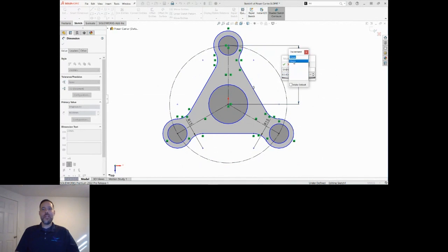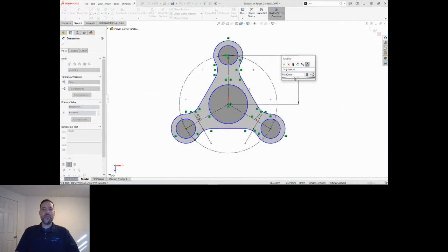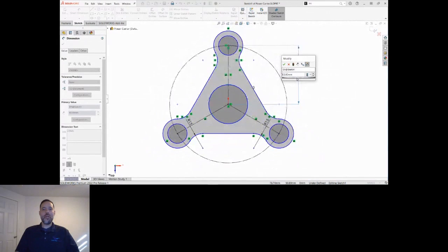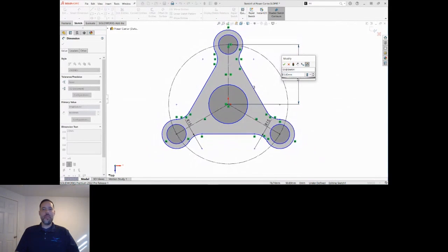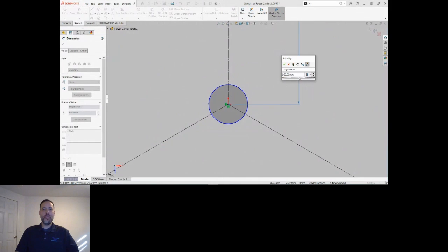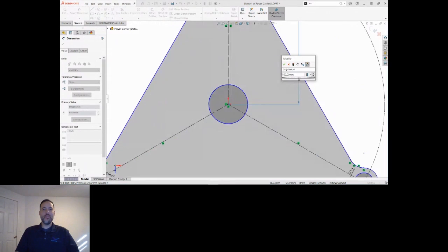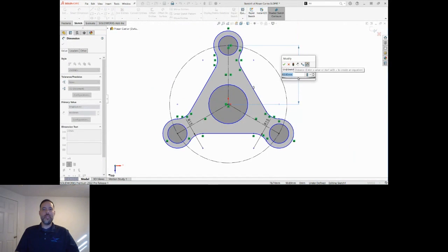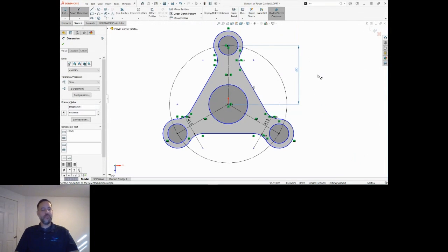So if you click on that, right now it's 10. If I click and drag this box, the spin box, there we go. It'll go up and down by 10, right? So I can make a quick sizing adjustment. If you hit Alt, it'll go up and down by 1, which is 1/10. And if you hold Control, it'll go up 10 times. Okay, so I can get there. So Alt is 1/10, Control is 10 times.